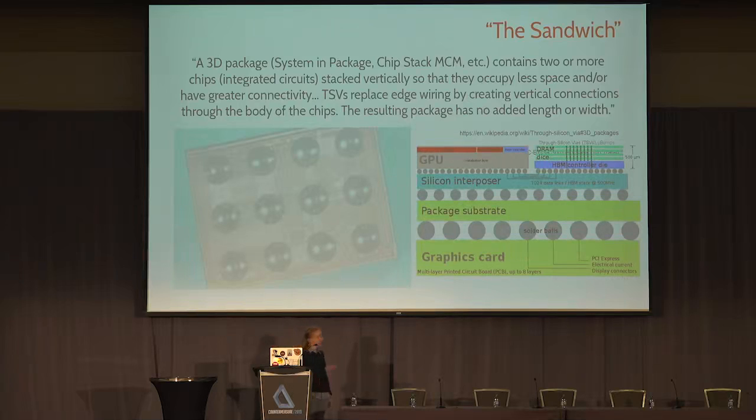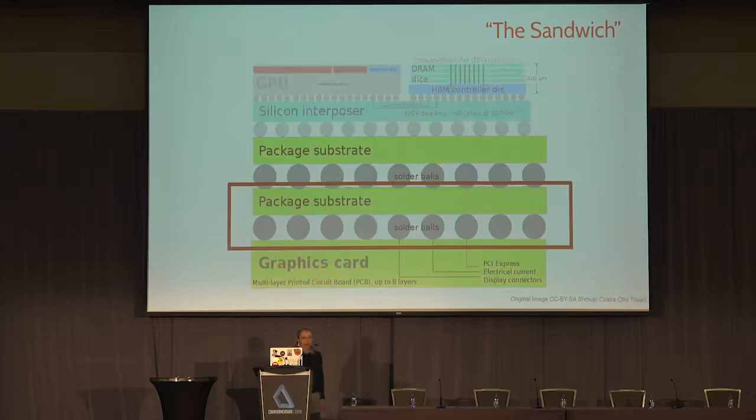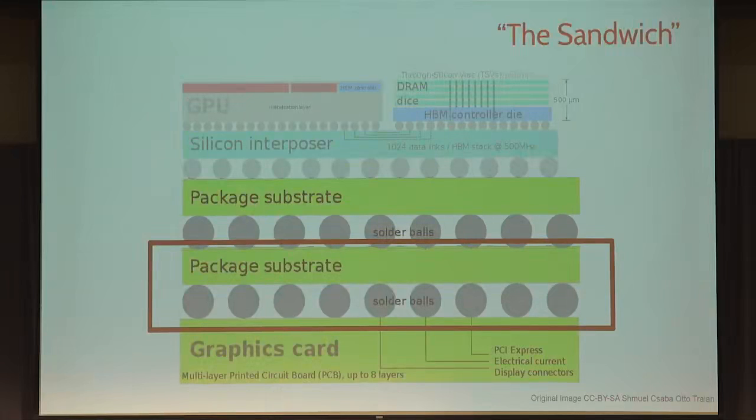Some of these vias might actually differ, and the differences in where vias are placed might actually affect certain initial security components of the chip, or might actually connect a completely different chip that's hidden in the sandwich. And so, for example, something could be hidden right here that you wouldn't see at the surface layer.